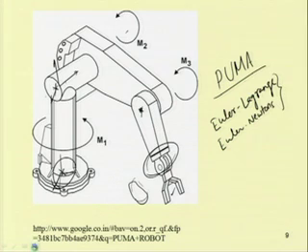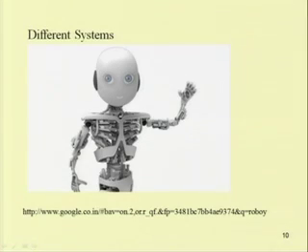Similarly, in the case of this humanoid robot, to move a joint, for example these fingers, one has to know what torque or force has to be applied by the tendon. There are several tendons in this humanoid robot, and one can also put motors at the joints. So, one has to find what force or torque is required at the joints in this robot. In that case one has to write the equation of motion.